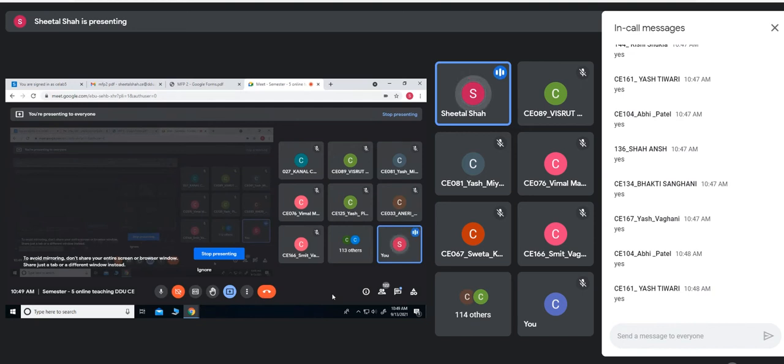In the IN or OUT instruction, the default register from which you transfer the data is the AL or AX register. If it is an 8-bit port, we use the AL register, whereas if it is a 16-bit port, the data is transferred through the AX register.